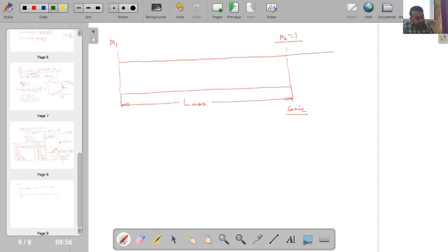If I take some additional length in this pipe, I have taken some additional length. Okay, so this is the L max which is giving us the sonic condition. Now more than this, we have extended some additional length over here. So it is pretty much clear to us. So say if I have to write down delta S total over here, so total entropy will be delta S from point number 1 to sonic condition plus delta S for the additional region.